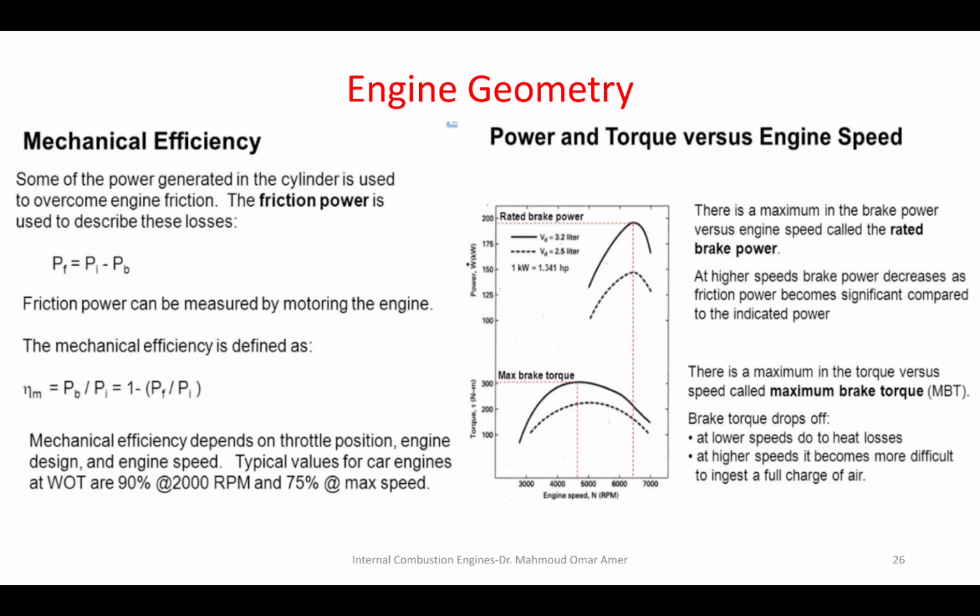So, when the power increases and the RPM is still low, the torque is high. So the torque is higher at lower RPMs. But the maximum power occurs at very high RPM, so you divide the maximum power by a larger RPM, and you get a lower brake torque. The RPM plays a role here.